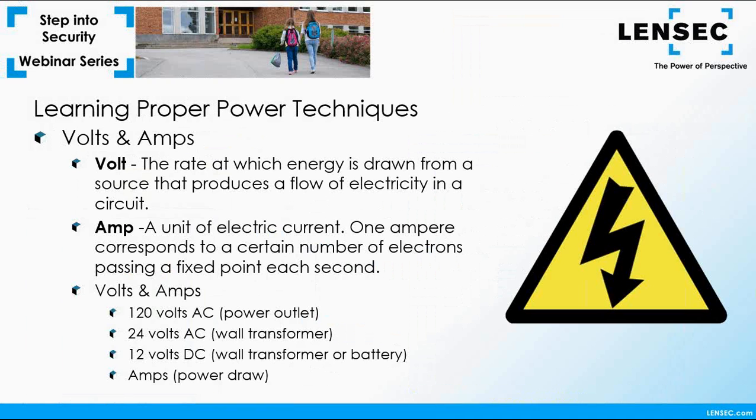Remember first, though, the camera running on PoE can be up to 328 linear feet from the switch before you have to inject power. Now, when you're talking about power from a separate source, whether it be 24 volts or 12 volts or dual voltage, power can drop over a distance. Voltage can drop over a distance.